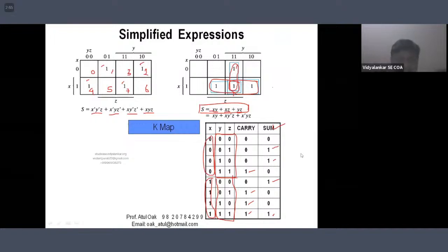And the third contribution is that the way I taught, you can group in twos. Same way you can do grouping of 4 ones. Such grouping can also happen. Grouping of 4 ones is also possible. Let me talk about it. Okay, and then I will quickly review how this particular x and y are changing. This means let's assume there is a 1 here. Unfortunately there is no 1 here, but if there is a 1 here, then you will find there are 4 ones which are adjacent. This is called a quad, QUAD.